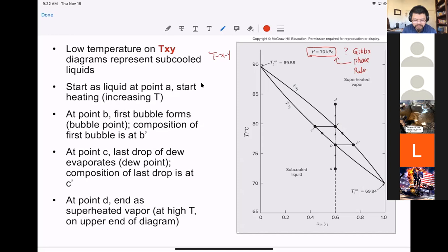So now if you look at the Txy phase diagram, number one is we need to figure out where would be the vapor line, where would be the liquid line. So that is to identify Tx and Ty, right? So I hope this is sort of straightforward. Increasing the temperature, of course, you are going to have the vapor phase. So the top region would be the vapor, and at low temperature, the bottom region would be the liquid phase.